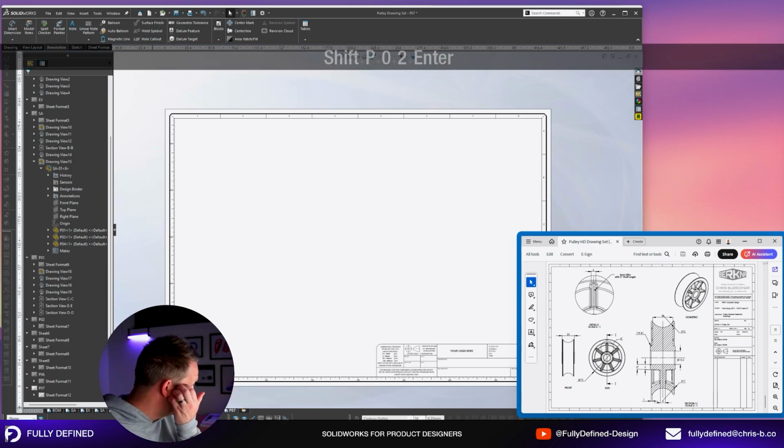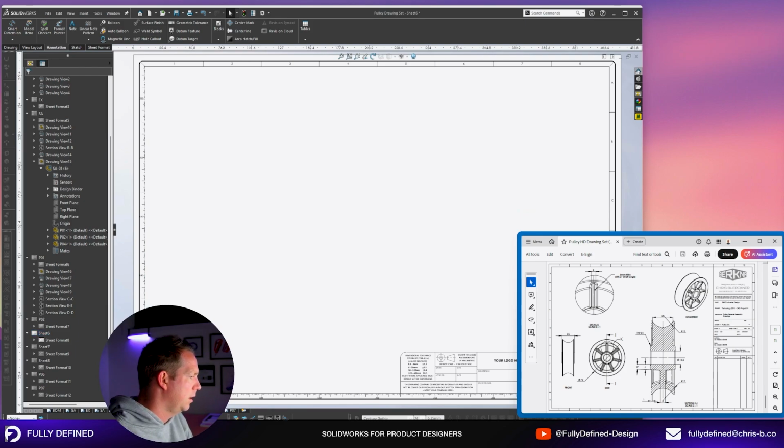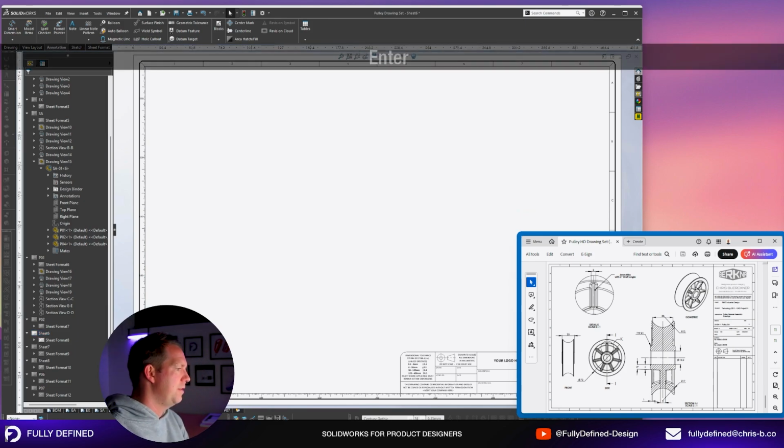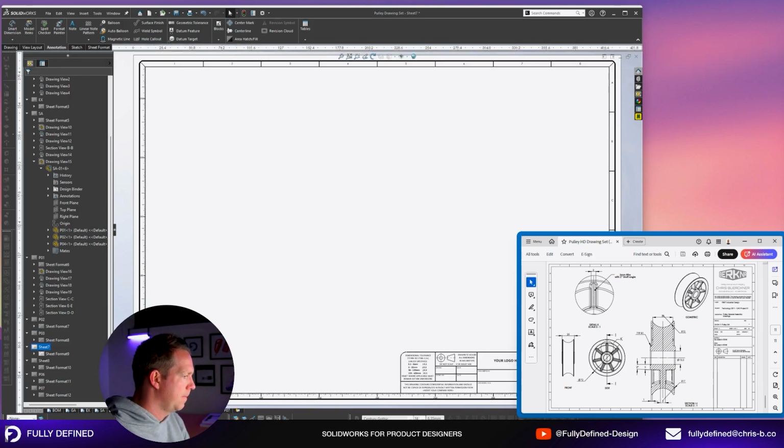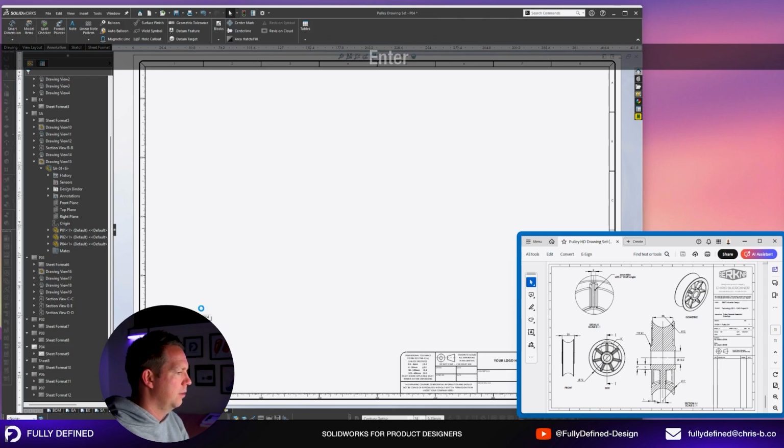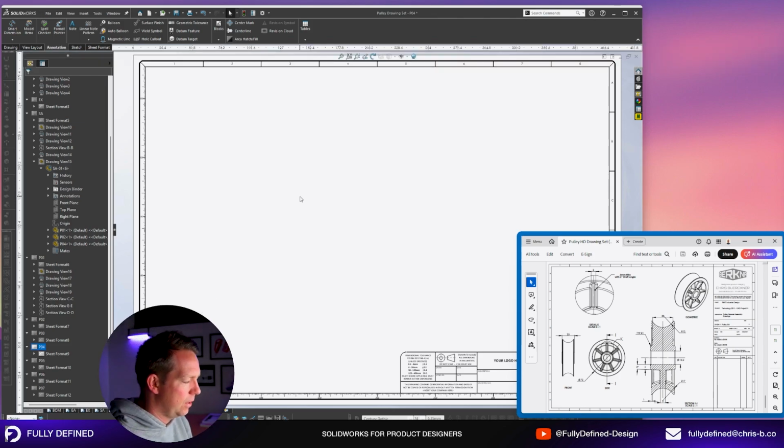And as I'm doing this, you're probably thinking to yourself, hold on, didn't we also have a nut and a bolt in our drawings? Where are we going to do drawings for those? That's a very good question. Now, normally, if you're manufacturing a product and you're specifying a nut or a bolt and you're making a custom nut or bolt, you would have a drawing for that hardware. However, in this project and in many projects that you'll do over the years, you're likely using off-the-shelf parts.